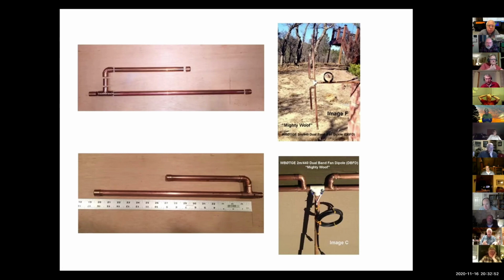Once the copper pipe gets hot enough and you are touching the solder to that joint, the solder will melt and just get sucked into the joint. It distributes itself all the way around the joint. You don't typically have to worry about putting solder all around.